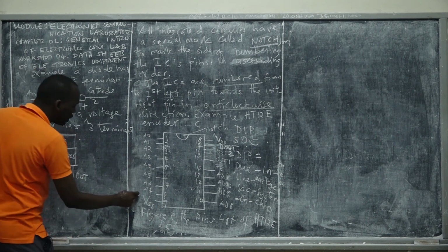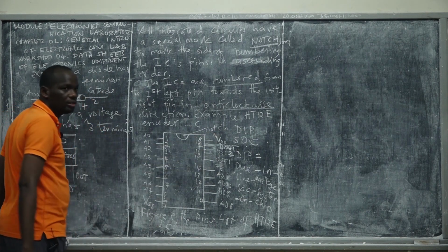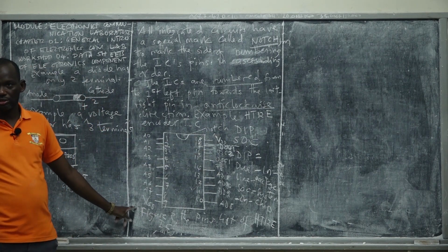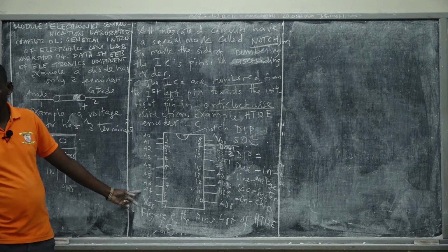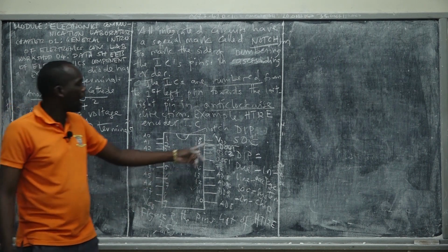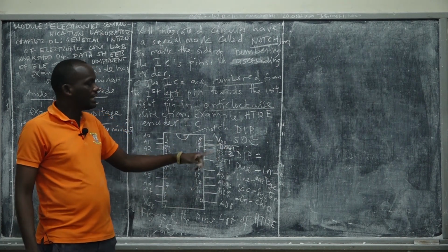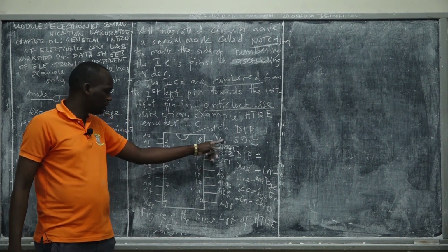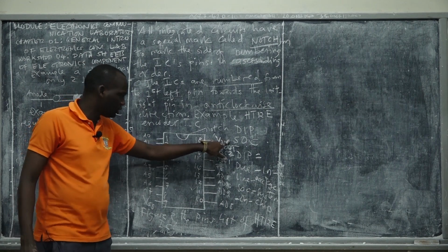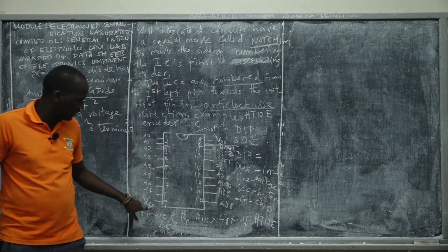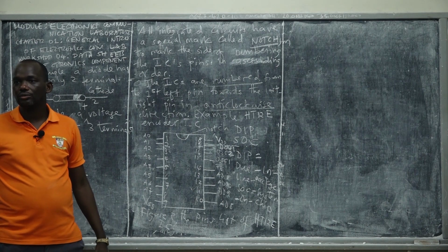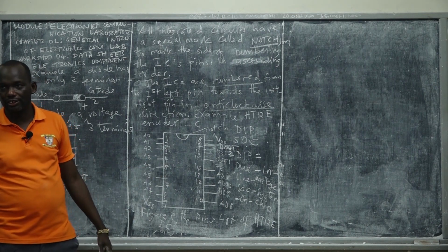Then, this is the address pin, ground pins, power pin. So you connect with ground at this point, or you provide 0 volt, right? And this one, you connect the power pins, or from the supply. So if you have your linear power supply, this will be the positive wire. You connect the positive wire, the negative wire. That's all. Then you have powered your integrated circuit.